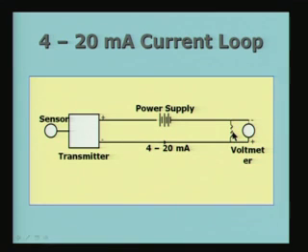The load is here, and across the load I am going to measure the potential difference. That means I am converting the signal, which might originally have been a potential difference, to a potential difference here at the user end, but I am using a current to transmit this information. So the 4 to 20 milliampere current loop is a standard feature in many instruments, and it requires an external DC power supply, usually about 24 volts, it may even be 12 volts.